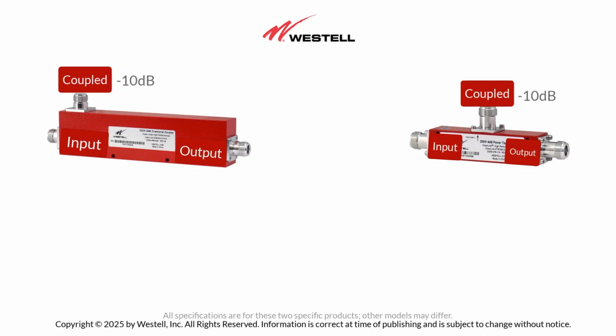If the coupled port has an attenuation of 10 dB, what is it 10 dB down from? This highlights one key difference between directional couplers and tappers. In a directional coupler, the signal power entering the input port is the reference point, meaning the coupled port will be 10 dB lower than that.